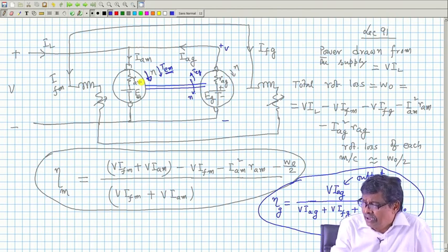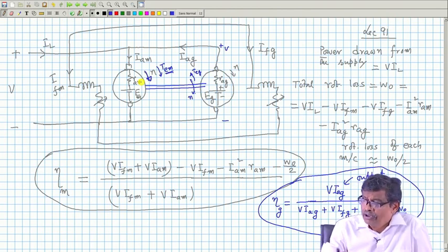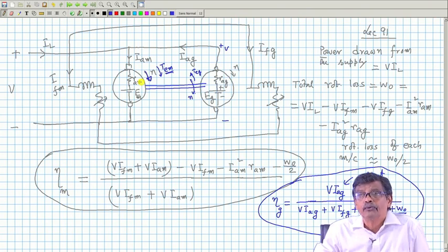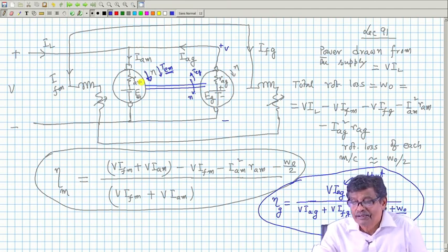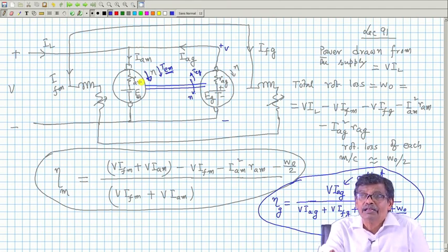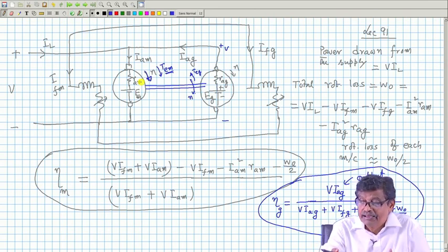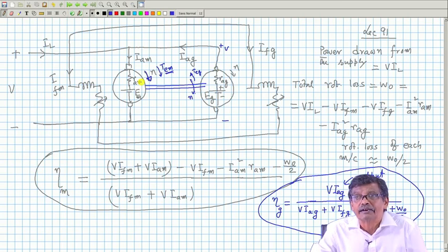So, this is how elaborately you can calculate. But the only thing I must tell is that this assumption that the rotational losses are same is not exactly correct. But anyway, that will cause a little error. At least you get the performance of the machine, temperature rise, etc., which can be well documented by really passing the rated currents through the machine armatures.